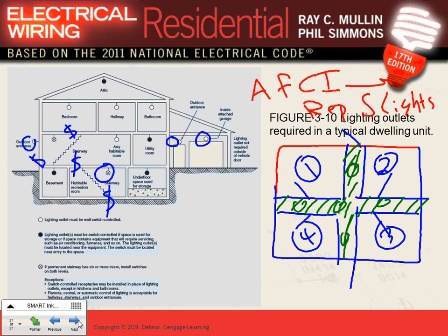Everywhere in the apartment, except, I'm going to write the exception because it's easier to write the exception. Cool? Everything except any place that, just to give you a hint, has a GFCI receptacle. Remember, the area that has a GFCI does not need AFCI. Okay, let's remember that. Which ones need a GFCI in an apartment?